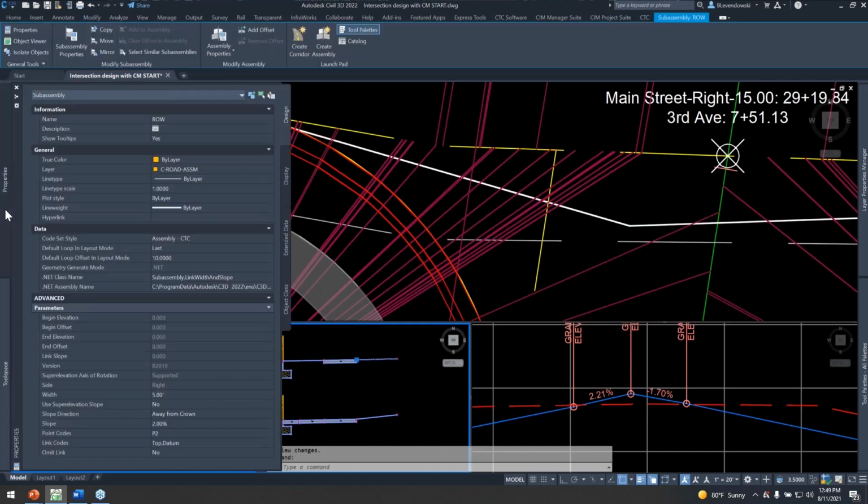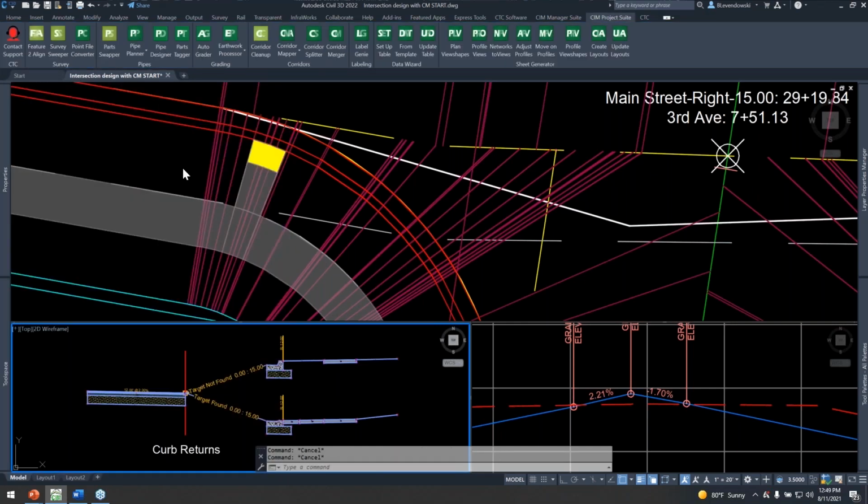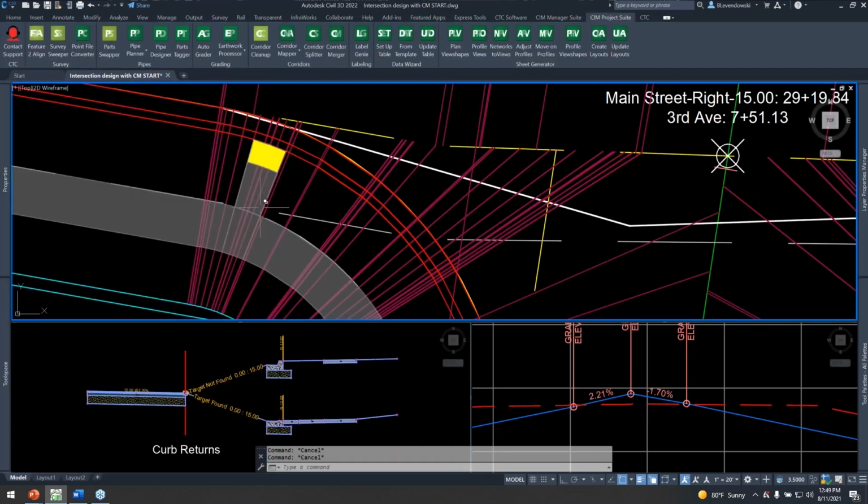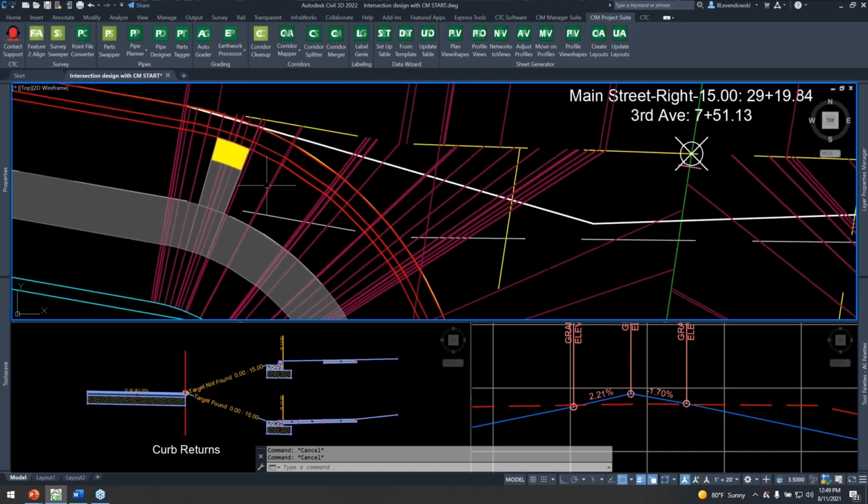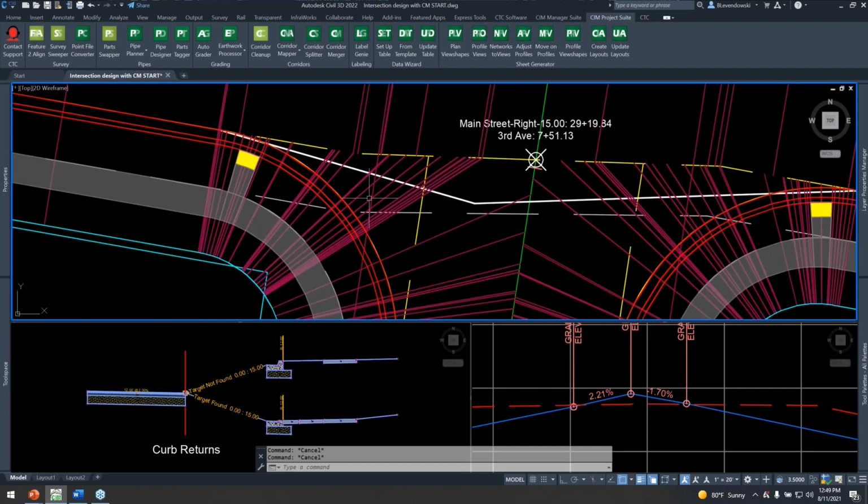That would be to turn off this option here, set this to yes, omit the link, and target that out and have it model your sidewalk, but don't model anything in between. And then use feature lines to just model that ped ramp area in between. You can even use some feature line style hierarchy to control some of that so it links to the sidewalk and to the start of the ped ramp or the back of the curb. Okay, a lot of different things we can use, just pointing out a few of those strategies.